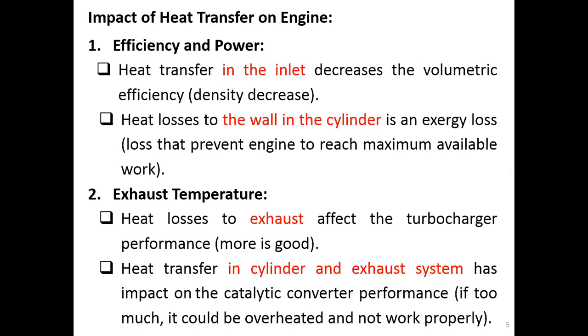How about the effects on the exhaust temperatures? If we have more or less heat loss to the exhaust, this will affect the turbocharger performance. If we have more heat carried out with the exhaust, that means more heat loss, but it means good. Good for whom? Good for the turbocharger, because the performance of the turbocharger is better with that heat loss to the exhaust.